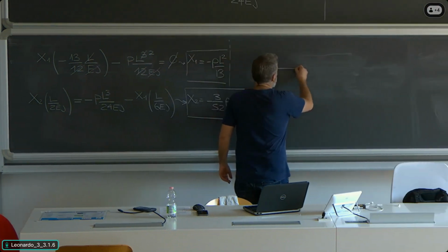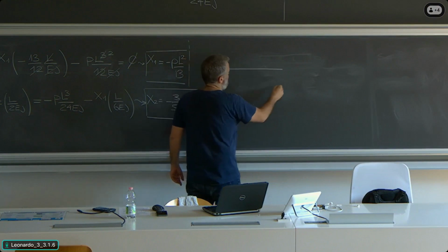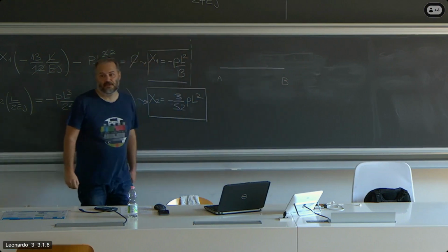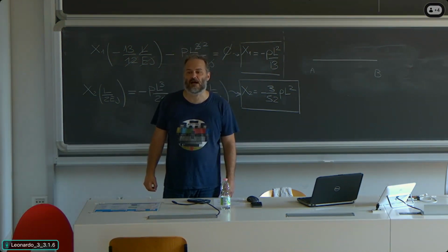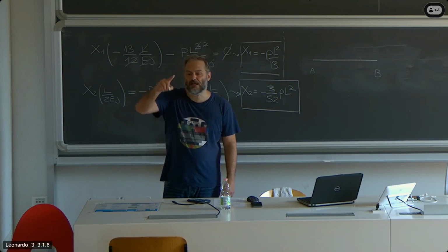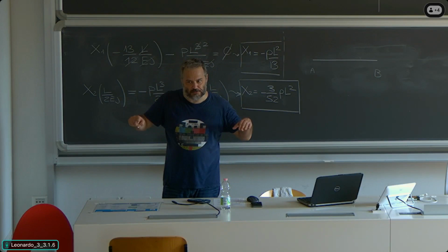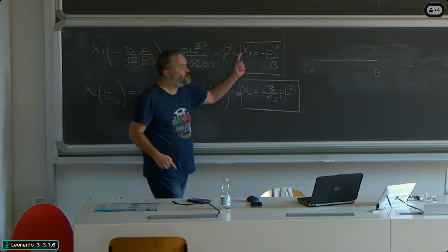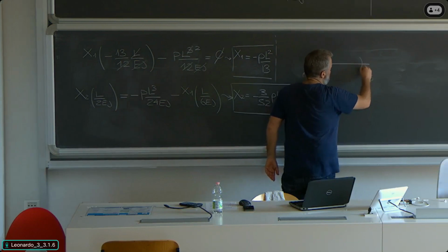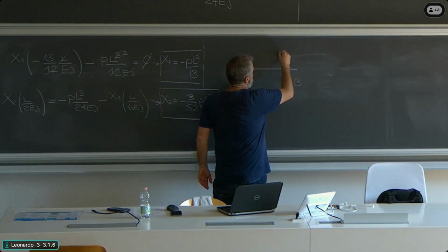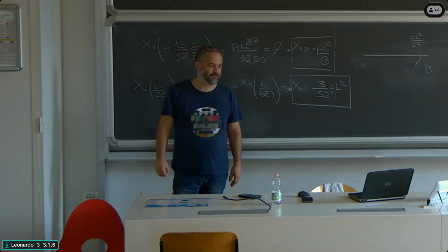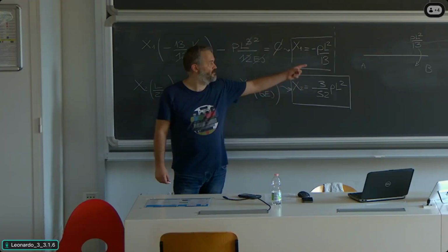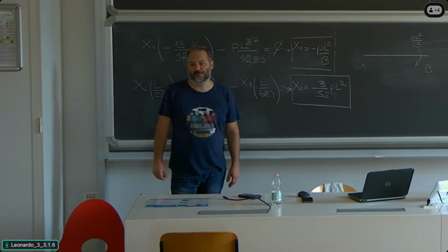So, first span, which is AB, how is it loaded? It is simply loaded by a bending moment at the second end, whose value is x1. Now we assumed x1 to put the bottom side in tension. We got a negative value, which means that on span AB, moment x1 looks like this. So PL squared divided by 13, this is what I get. And tension is at the top, as it is usually the case when you have continuous beams over the supports.